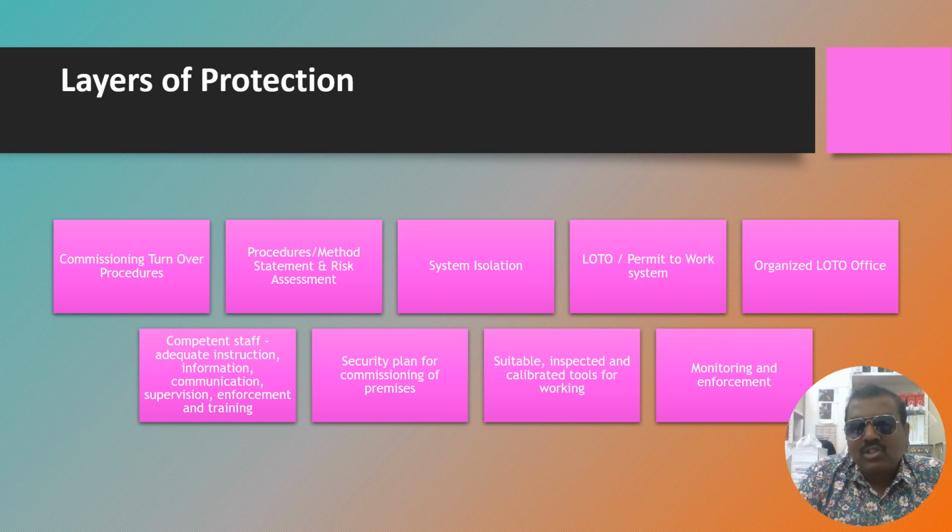As I said, come to the second box. What is written here? Procedures, method of statement, like that. Okay, in these conditions, think that it is a transformer. Maybe 13.8 is upstream and the downstream maybe it is 480. This 13.8 feeds to one primary transformer and the secondary will be 480, and the 480 will be feeding to an electrical panel. That electrical panel also will be having another 5 to 10